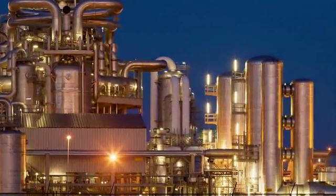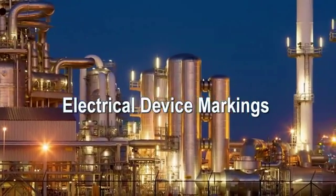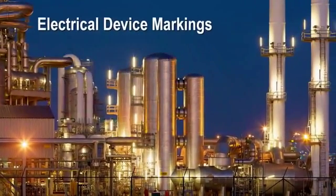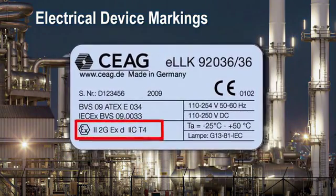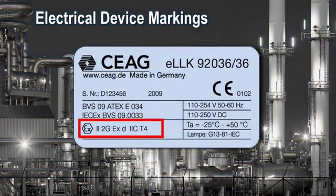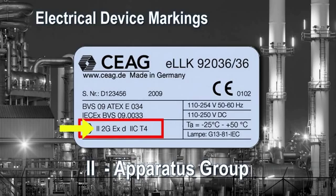All equipment certified for use in hazardous areas must be labeled to show the type and level of protection applied. In this example, we will review a fluorescent light fixture within a hazardous environment. The first identifying mark will reflect the apparatus group by hazardous application. A 1 would indicate usage for coal mines, while a 2 would indicate general industrial environments.